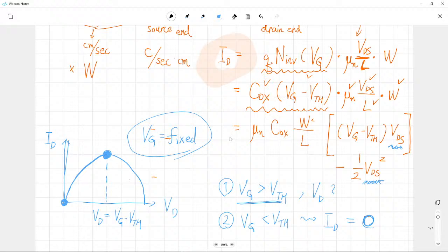The point where your derivative vanishes corresponds to the point where your drain current is maximized, and when you apply this expression, the peak value we can achieve from this structure will become clear. Yes?